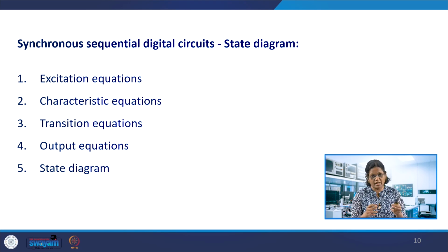If a state diagram is given, can I get the digital circuit for it? Verilog modules can be developed in two ways: for the digital circuit as such by instantiating all of the components, or considering the state machine of that digital circuit. For a synchronous sequential circuit, clocked, one should have the privilege to do it in terms of the state machine. So let us see this.